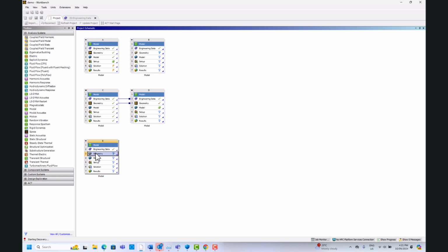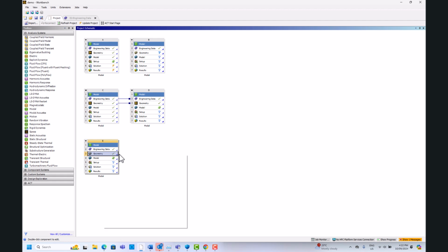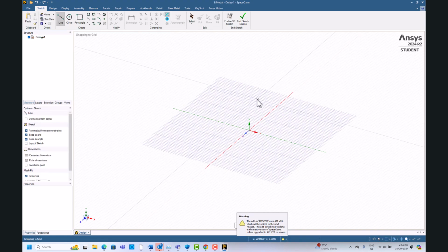Then the second step is to define the geometry. Then you can import the geometry into your system. So I'll just right click and go into the sketch plane. Okay. There are different package options that you have. So you go into the sketch plane, and all you need to do is draw a line. Because we need to pin at a point, it's better to draw in 2 segments. All right. So like I said, all we need is just to draw some lines.